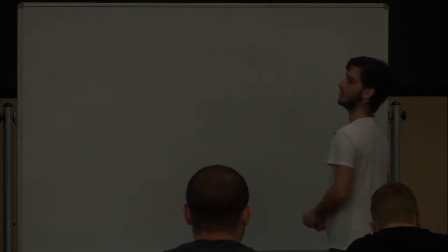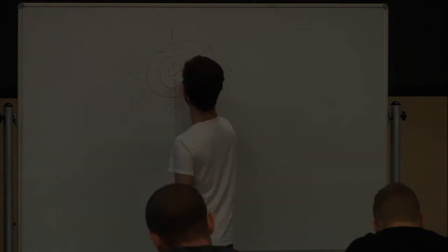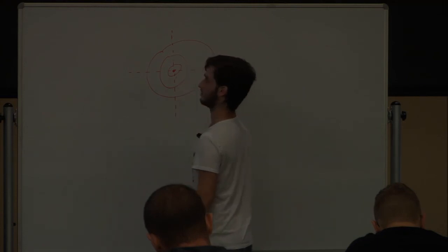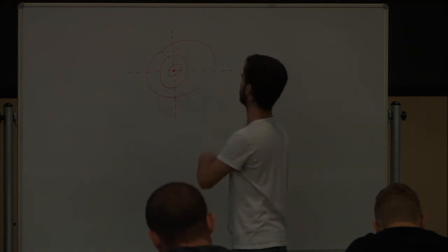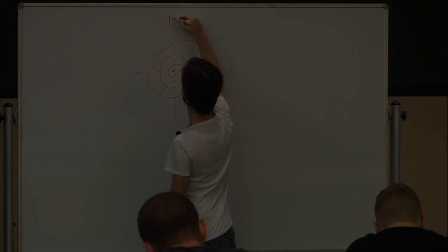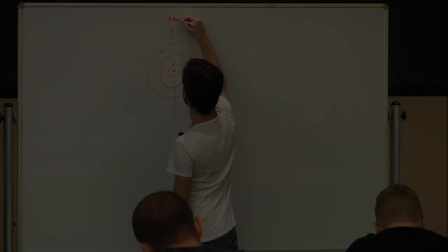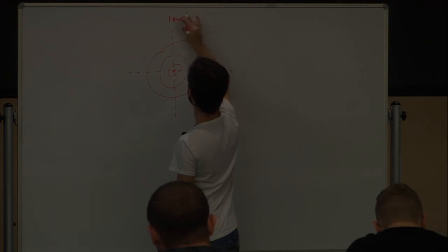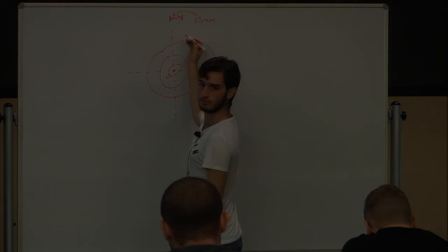The cam is subjected to a couple moment of 5 Newton meters. So we have to determine the minimum force P that should be applied to hold the cam in position. So then this is a maximum static frictional force problem. So drawing the free body diagram is right in the middle. Oh, 10 millimeters. Let me write that clear. 10 millimeters. So 10 millimeters away from this point, a normal force and a static frictional force there.